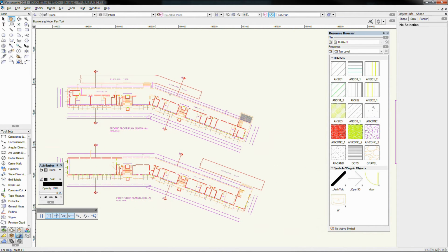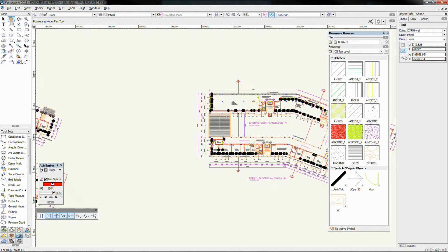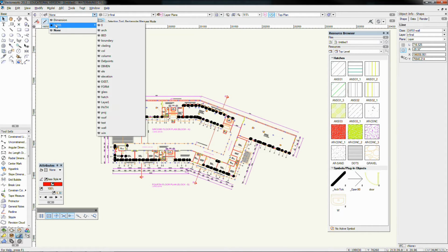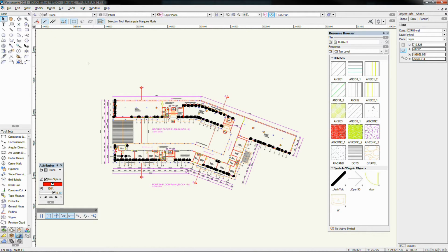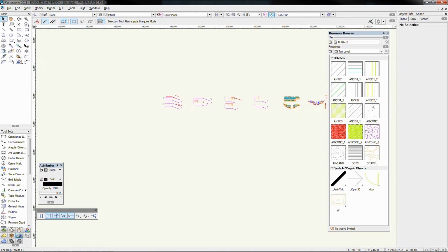Now all of this is snappable, all of these are line drawings here, and probably some of it's been brought in as boxes, so you can see I can pull objects out. Just having a little think as it's trying to catch up with what I'm doing here. And probably later on I would then break this down from its current classes. You can see it's broken it into our DXF01, and here's all the different classes here, and I would go through and turn each of those on and off, and probably select each of these here and make them an individual layer as well, just so I could get rid of some of this data, because as I zoom out even further you'll notice there's heaps going on here.